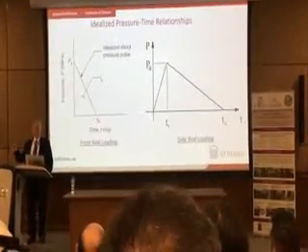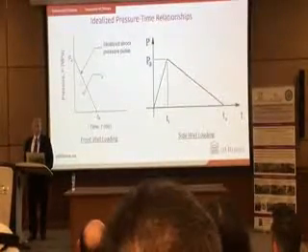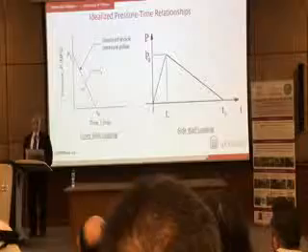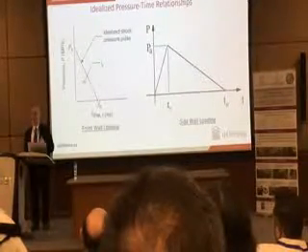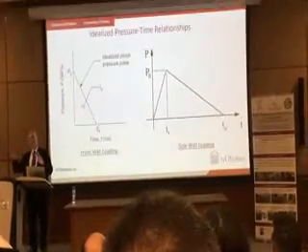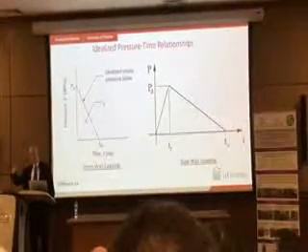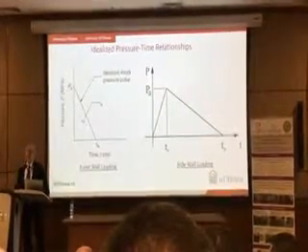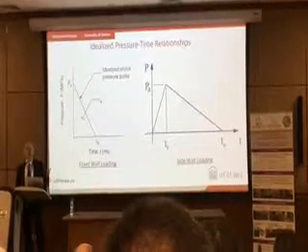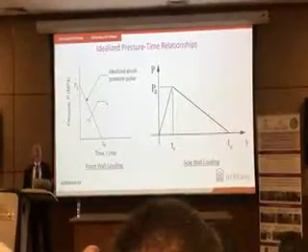Often, what we do is we find out what is the reflected pressure and duration and impulse. So if I take impulse multiplied by 2 divided by pressure, that gives me duration. In other words, I find time such that area under actual distribution is equal to area under the triangular linear distribution. This is idealization, and we almost always use triangular distribution, right?